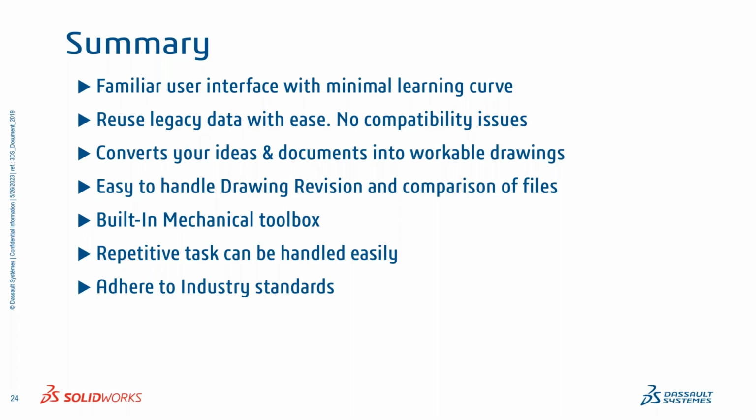And you can convert your ideas and documents into workable drawings with the help of image tracer. What I showed earlier, you can convert images to DWG entities, and the same goes for your PDF drawings. PDF drawings also can be converted to workable DWG drawings with the help of DraftSight's particular tools.